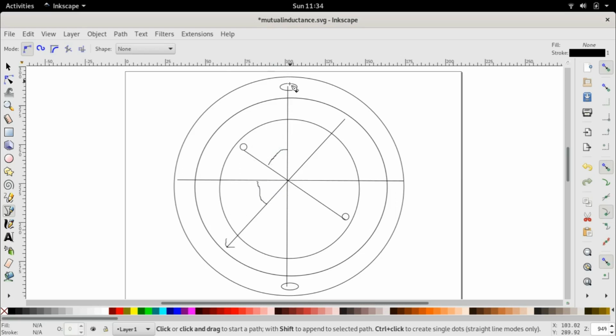So the mutual inductance caused by the excitation of the stator, due to the flux linking with the rotor, has a cosine relationship, and so does the mutual inductance when the rotor is excited and we are calculating the linkage with the stator. So they are mutual. Of course, not all magnetic systems are completely mutual. Sometimes there are differences, but in a vast number of cases, when one mutual inductance has a certain functionality, the other mutual inductance also has a similar functionality.